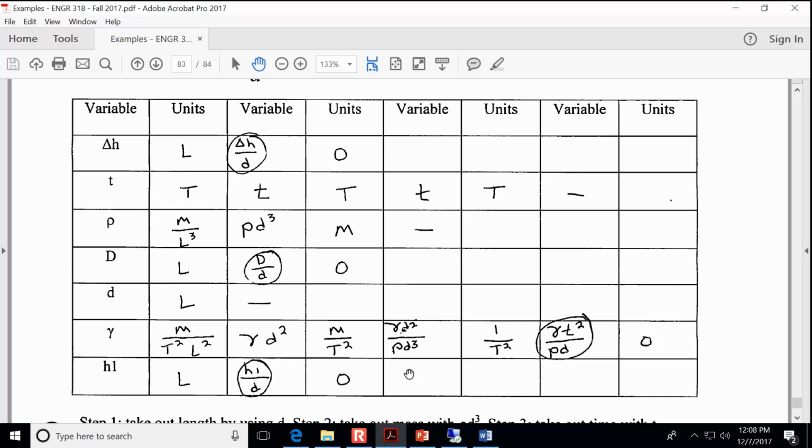And so you could use any one of them to start canceling out the L in the other ones that remain. But in the end, when you go through all the combinations, you're going to have 4 pi groups, and I put a couple of the combinations at the bottom of the page there. And so what this process tells you is the variable combinations that would exist in the equation. And so it would give you a guide, for example, of data to graph, like if you're going to be visualizing data of the experimental results.